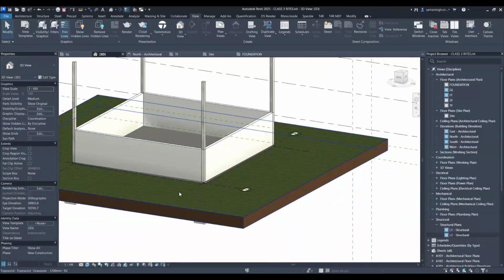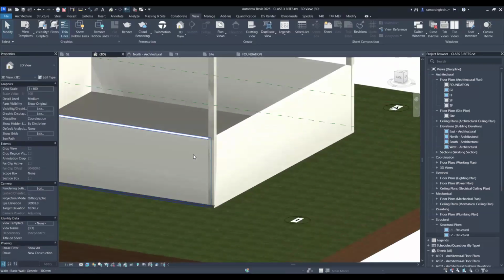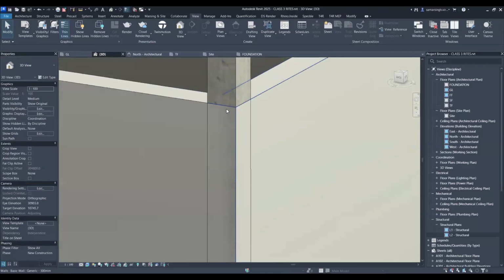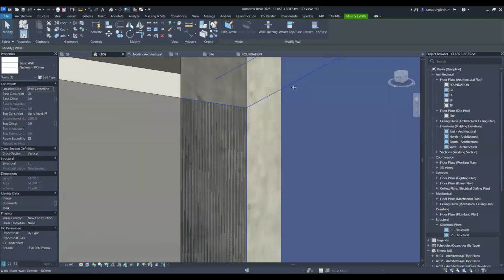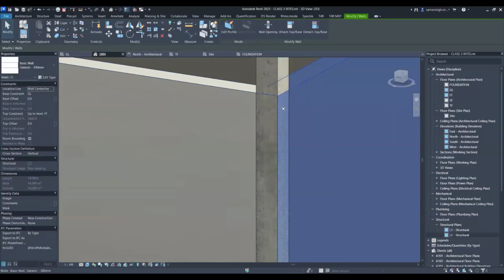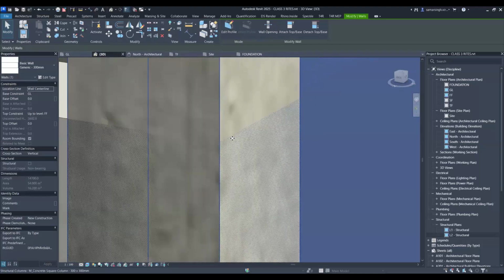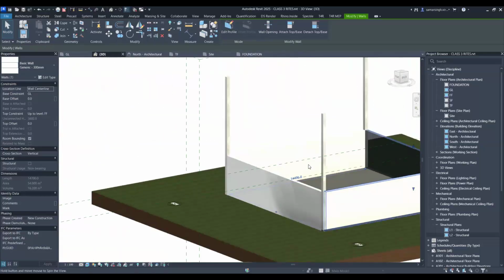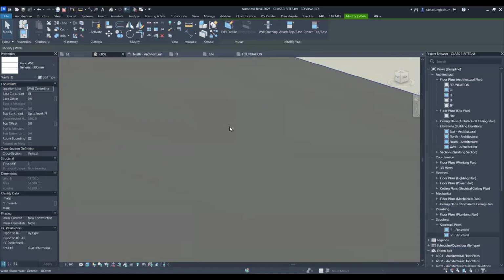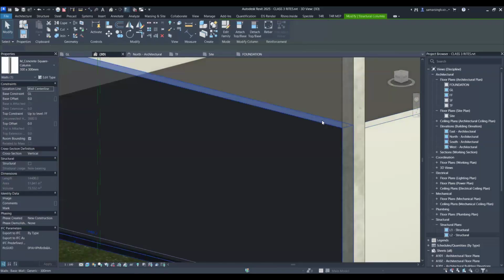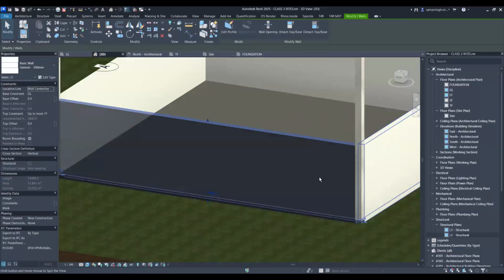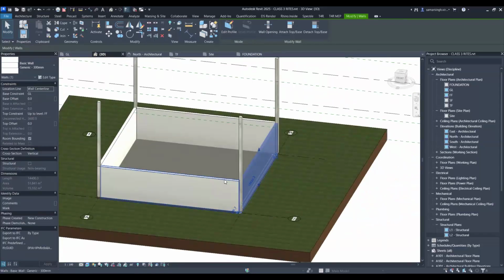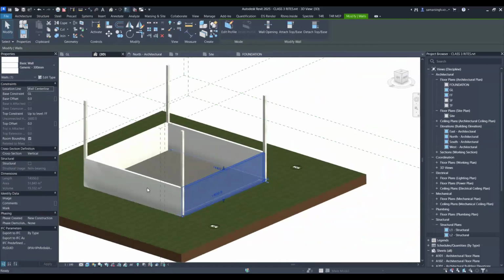All right, so walls have been made, but when I zoom in, you'll notice a problem. You can see that this particular wall is actually going through this column and connecting with this wall. Because of that, again an overlap geometry is being created. So again, a very common problem while drafting, this happens a lot. So to maybe solve this, okay, on this side it is not happening, I think. Ah, yes, it is not happening because I took center to center.